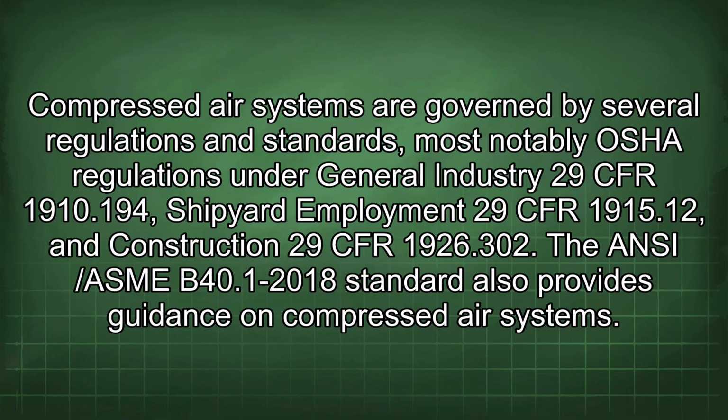Compressed air systems are governed by several regulations and standards, most notably OSHA regulations under General Industry 29 CFR 1910.194, Shipyard Employment 29 CFR 1915.12, and Construction 29 CFR 1926.302. The ANSI/ASME B40.1-2018 standard also provides guidance on compressed air systems.